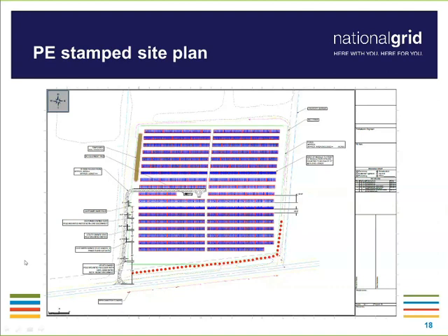And then another good key component is the actual access road. Now that access road is key because if we have to get back there to inspect equipment, access to the site, at minimum to the overhead service point, is a requirement. So to have that access road illustrated is good engineering practice because it will be required. And we need to be able to have that shown and make sure it's built satisfactorily so we can access equipment that National Grid as a company would be interested in inspecting, or equipment that we may have to own or operate from that facility.